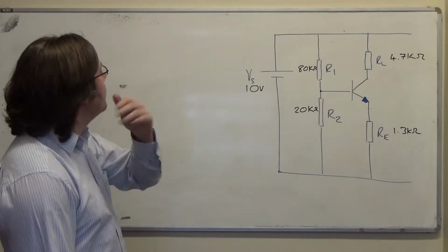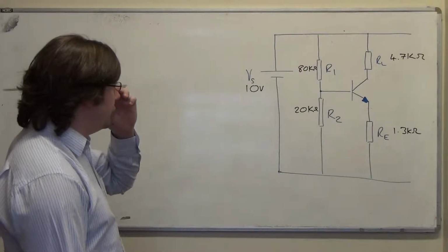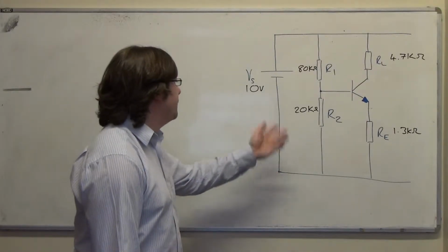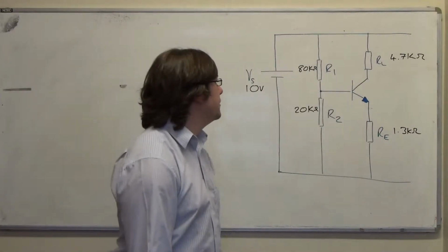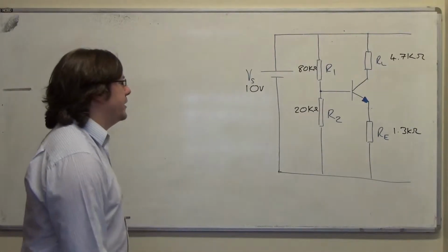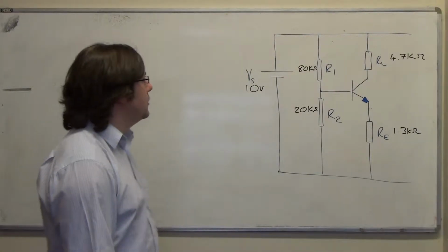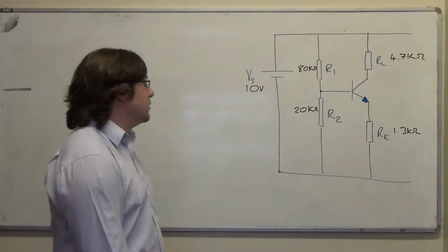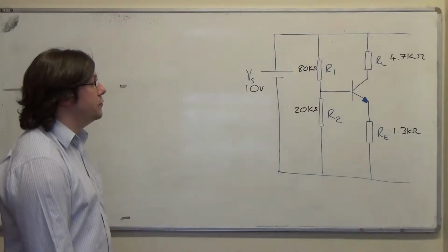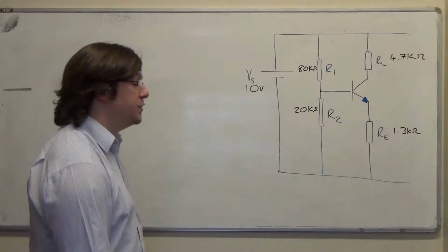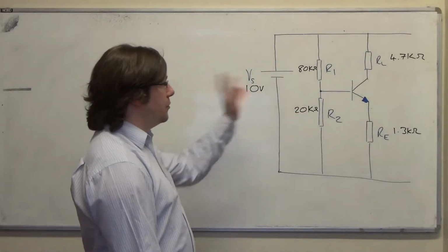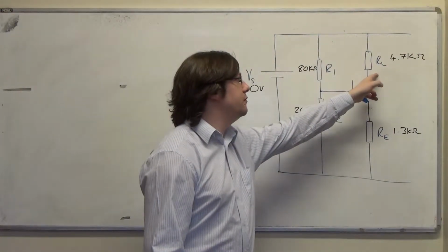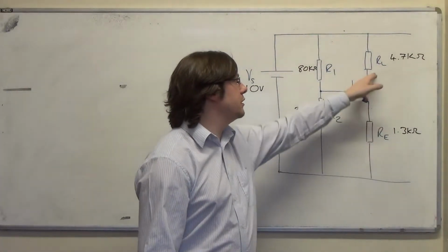So there are lots of ways of attacking this. You could, if you wanted to, take equation 7, which was VS minus everything for IC, which is 1 over RE brackets VS times R2 over R1 plus R2 minus 0.7 close brackets times RL, if you wish. And just sub in the numbers, and out it will spit the quiescent value of VC. So here's the ground, which is what I have as my VC.